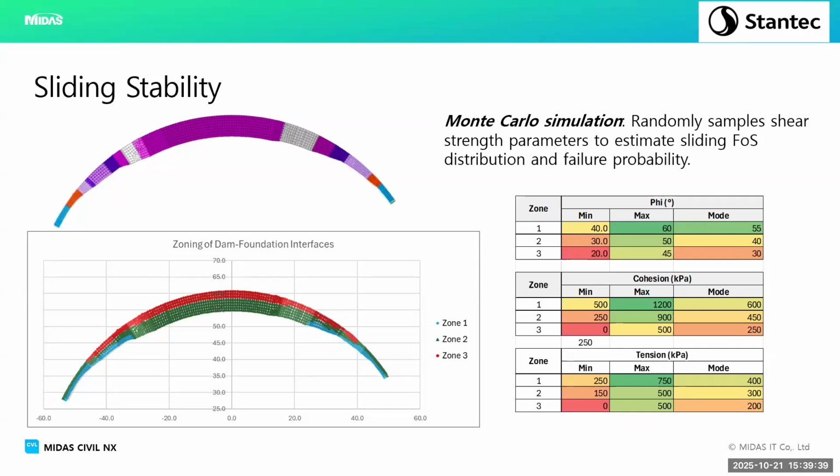The zones can be numerous. If we do have a geological feature running along one abutment of the dam or whatever have you, you can replace that with a different zone, a different material parameter. Again, this is all post-processing, but the post-processing is easy due to the ease of extraction and the compatibility with Excel. It would not really be as user-friendly if it wasn't. And for MIDAS FEA X, I'm looking forward to the API so I can do something that Willem's been doing.